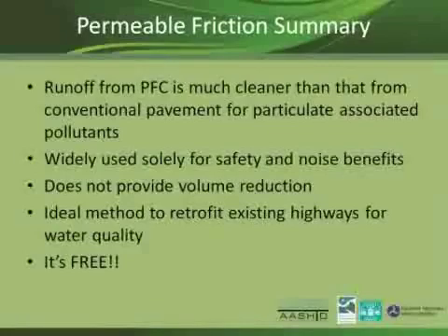That's my other bullet I forgot before. It's quite a bit quieter. They just did a redo of the freeway through Austin that goes through a lot of residential areas, and there's a 7 decibel drop in noise when they did that. A downside is that there's not much volume reduction. There's some delay in peak and attenuation of peak at modest rainfall intensities, but if you're under a real LID scenario, it may not get by the regulator unless you have no other options.